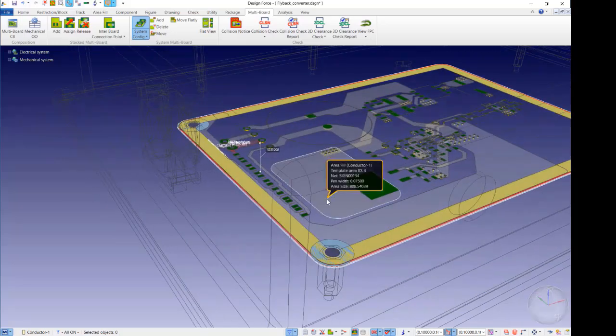So that's the end of the demonstration. In summary, what we've done is we've added some rules at the schematic stage. We brought those rules forward into the PCB. Within the PCB, within our rule section, we've set up some voltage clearance classes, and this time we've based them on IPC 2221. And I showed you how to enter the external conductors uncoated.